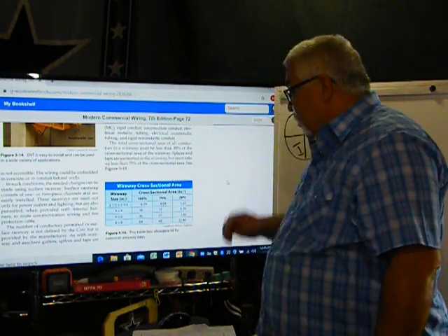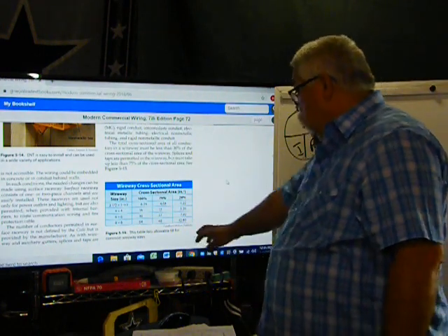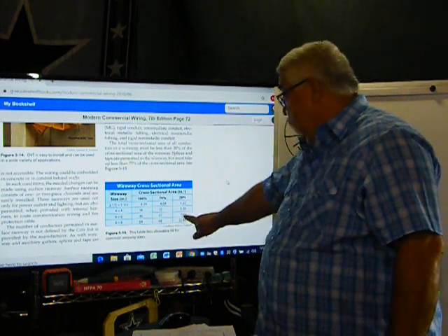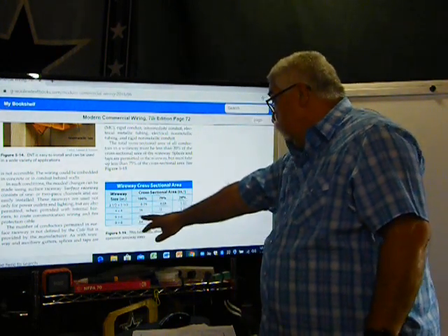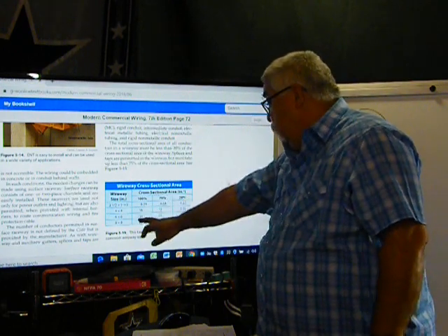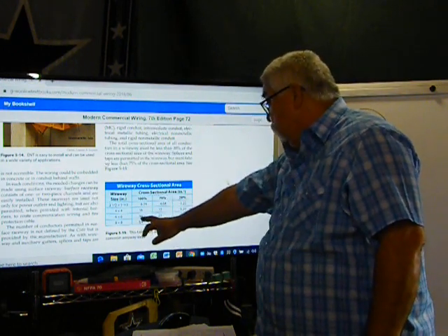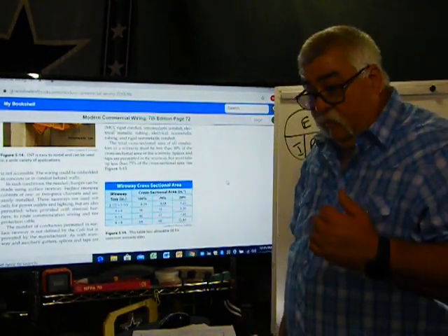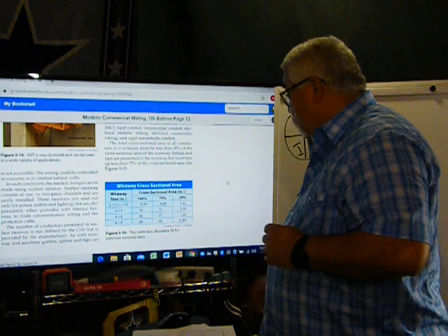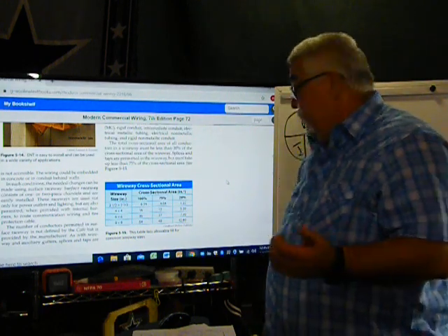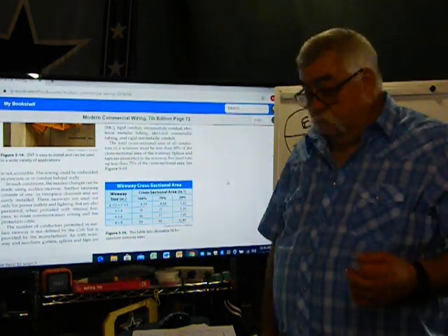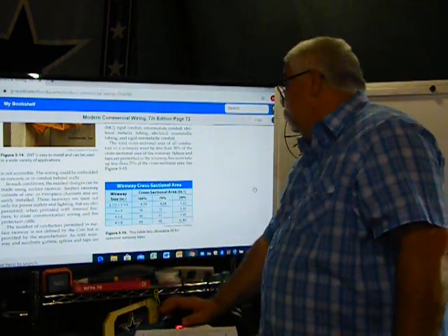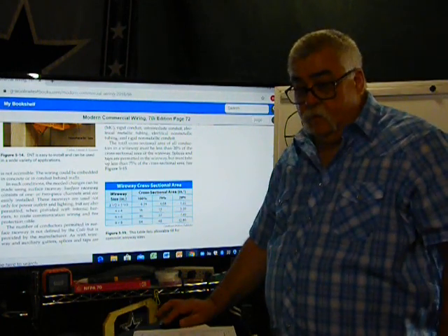So on that other one we will need an 8x8 box because we're under 20%. Okay, 20%, 6x6 is 36. 20% times 36 gives us 7.20. Okay, we were at 18.85, so we have to go to the next size up. Okay, looking at this table, an 8x8. Because an 8x8, that 20% is 12.8.